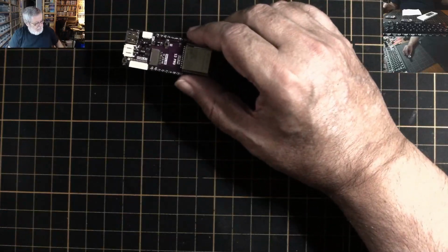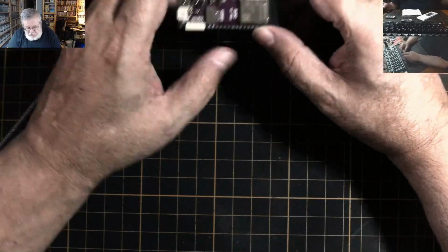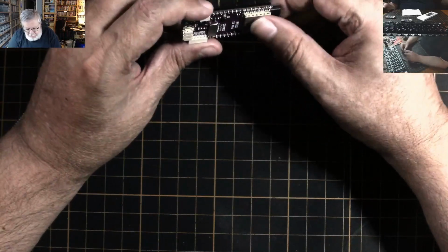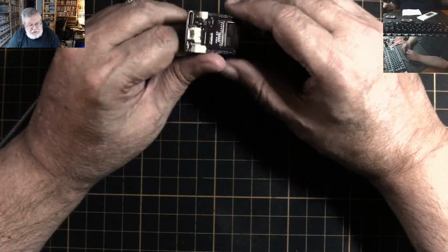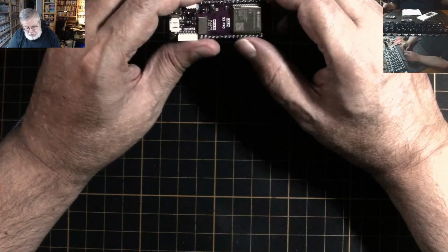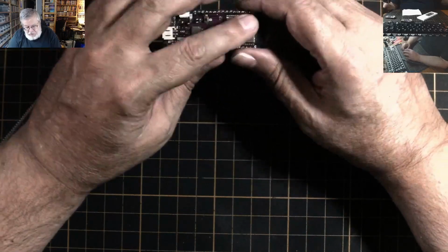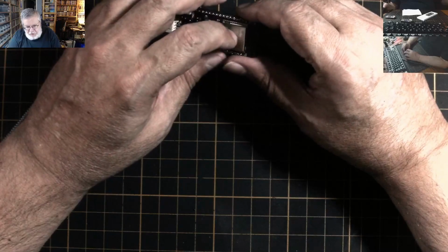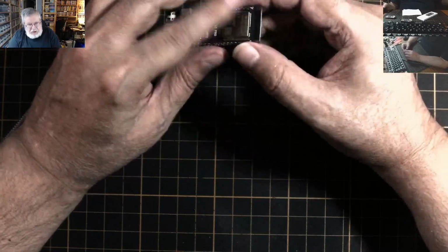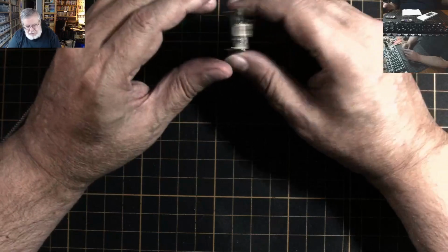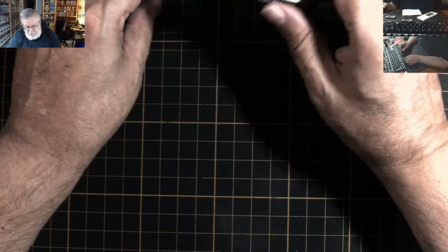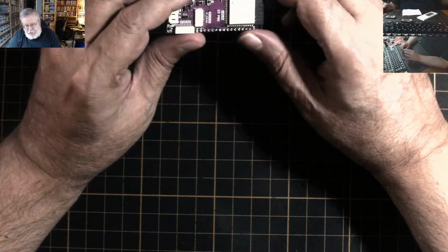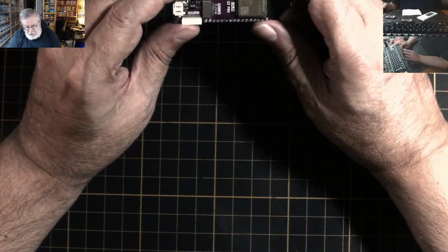So it turns out it wasn't dead. At first I had done a flash erase when I was testing this, and it wasn't erasing. It got stuck. I slowed it down, like the baud rate, and sure enough, I finally got it to flash yesterday. And then once I got it flashed, after a couple of tries, I got it to flash the bootloader, and then put the CircuitPython on, and now it all works correctly.